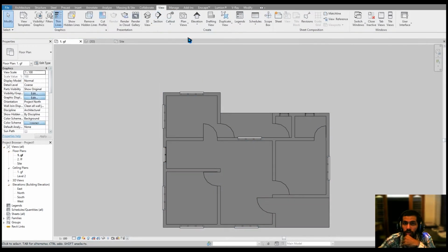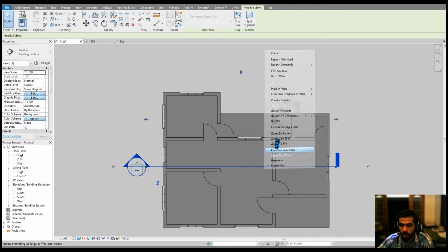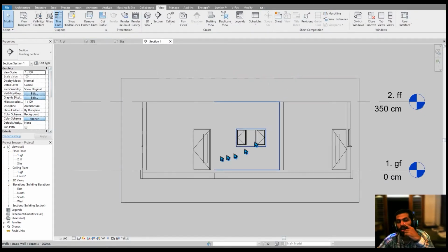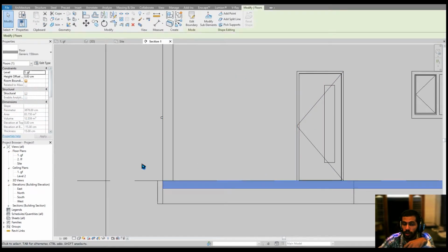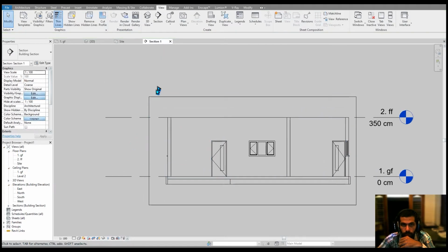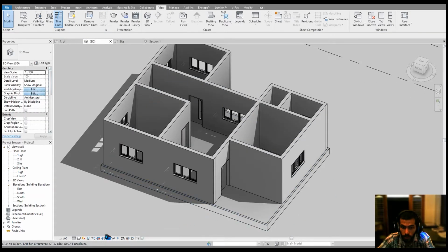And if you try to place a section right here, get into the section view, you have to see that the wall should cut away the floor here. So the floor and wall will be quite a different structure. So you have to convey that right into Revit by providing attach button and detach the targets. So that's how you'll be placing floor.